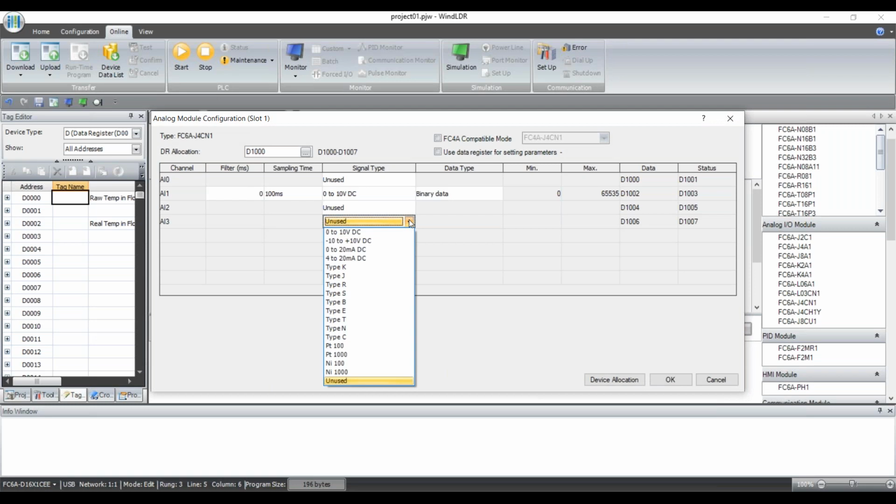If I'm scaling pressure here, and you've got something that goes below 4, what I would do is use the 0 to 20 milliamp setting to catch that. But in either case, whatever you use here, 0 to 20 or 4 to 20, is what's going to be used to capture. So if you do use a 4 to 20 milliamp setting here, if you get something below 4, that's not going to affect your values here. It'll ignore it, okay? If you use 0 to 20, then anything above 0 milliamps will be affected in the scale here.